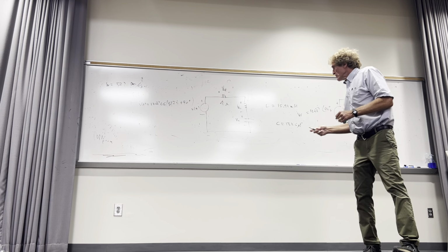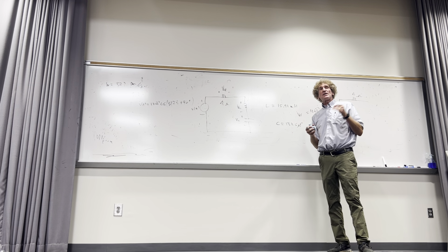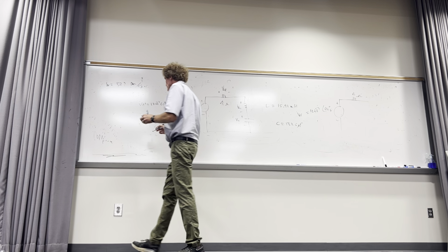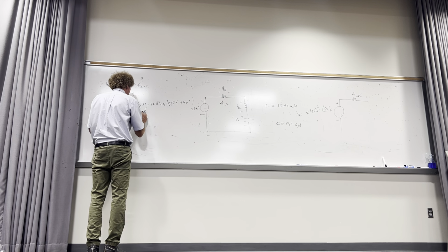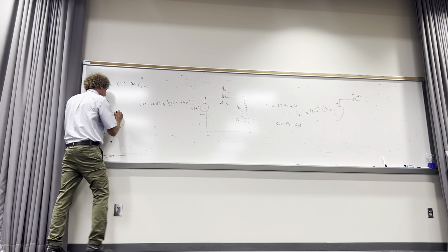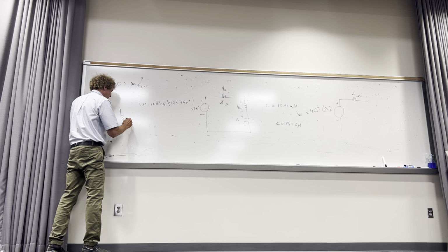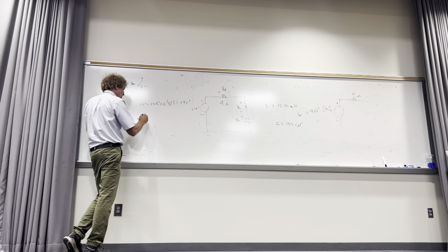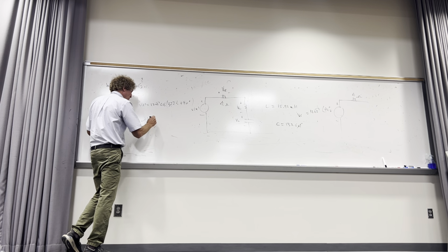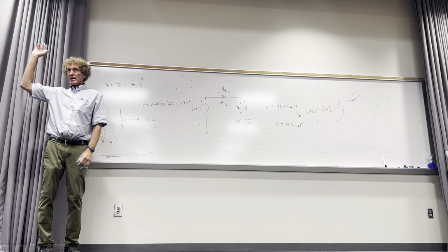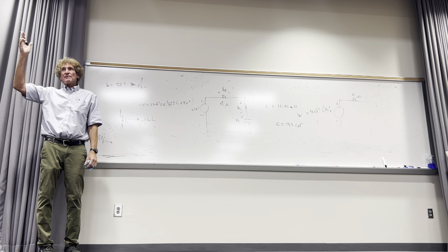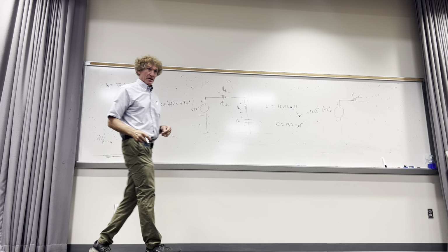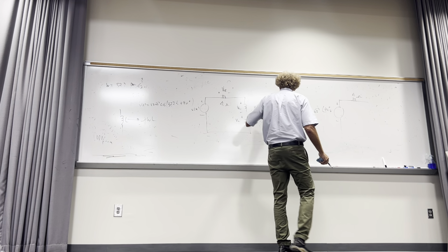Next, what do we do with this inductance? The inductance is 15.92 millihenries. And do you remember the actual value of the impedance of an inductor? If you had an inductor here of a value L and you wanted the impedance, the complex resistance, it would be what? J omega L, right? How many remember that? You'll need to know this very well. It can't even be something you wonder about. This has to be automatic, like 2 plus 2 is 4 kind of thing. So what would the impedance of that be?